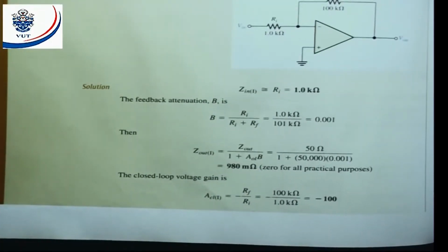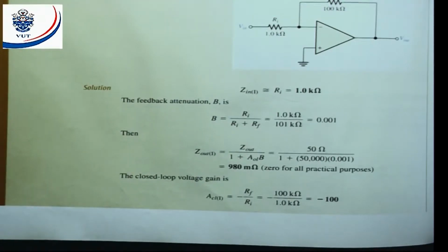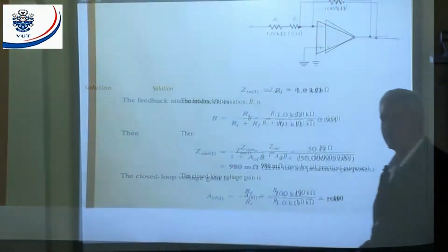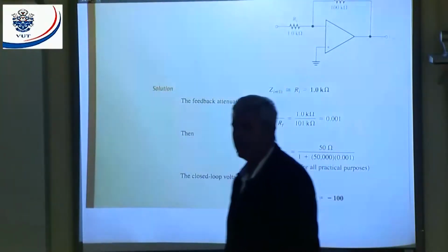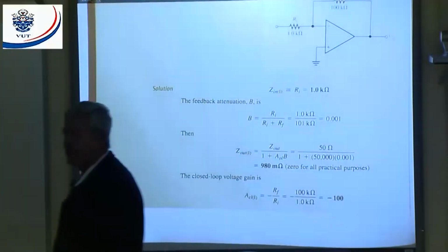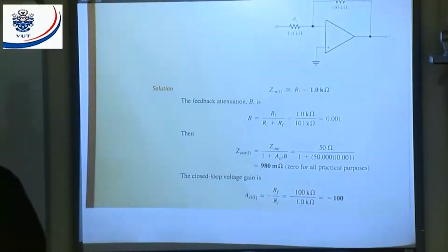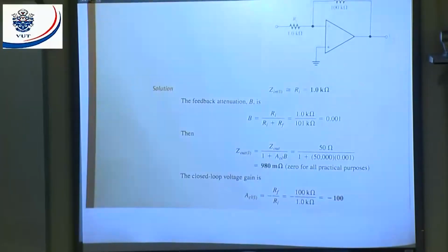All right, the next part of the work, 12.6, bias current and offset voltage. Why do we talk about bias current? What is the input stage of op amp? Anybody? What is the input stage of op amp? It's a differential amplifier. And we got transistors. When we got transistors, we have to bias, all right?